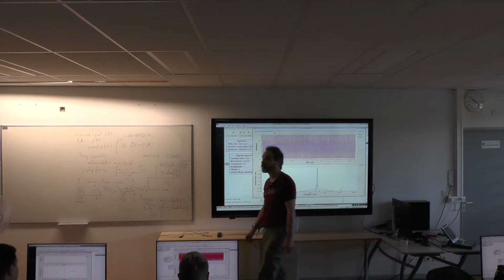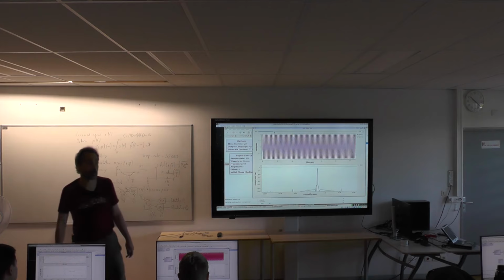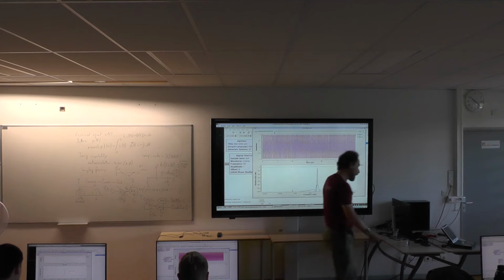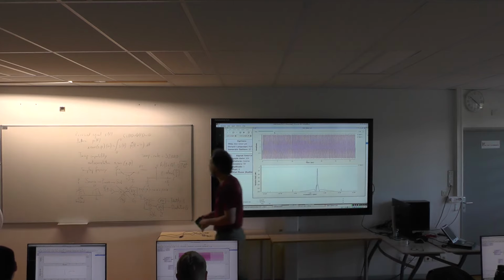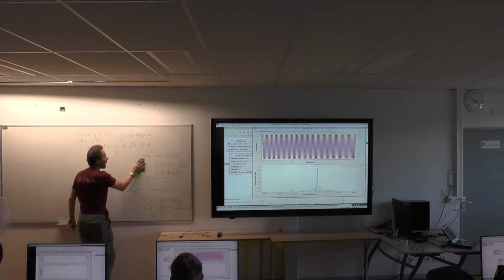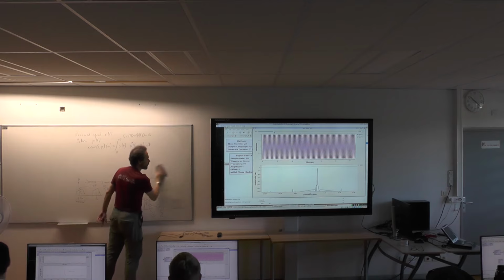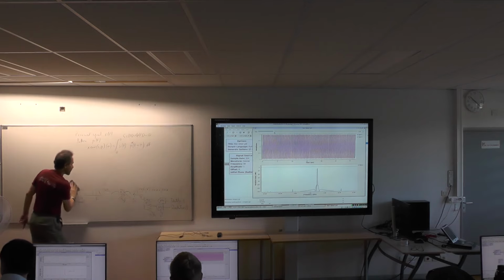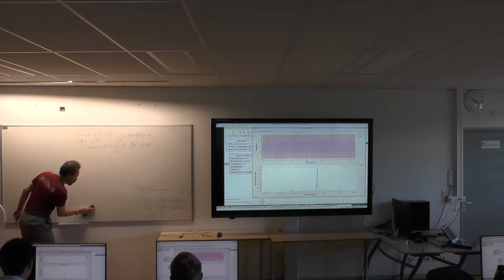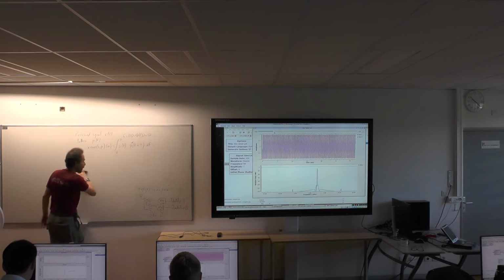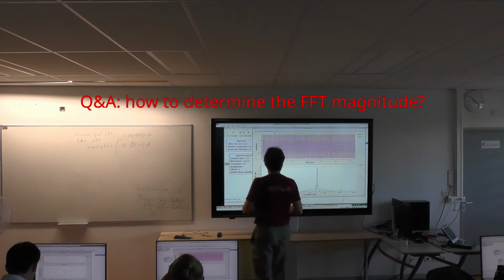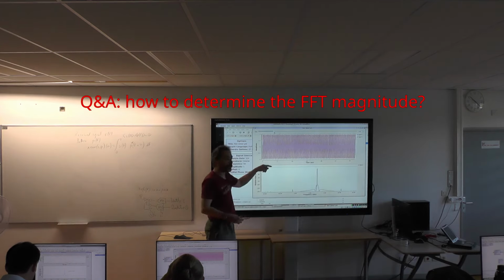Okay, so I hope you're all convinced that GNU Radio is a lot of fun for testing signal processing concepts. And we just spent quite some time discussing that what we want to perform for analyzing time transfer is correlations. So let's select the correlation block in GNU Radio. This way we will be able to assess our understanding of how a correlation is performed. The amplitude of the Fourier transform depends on the normalization that you select.